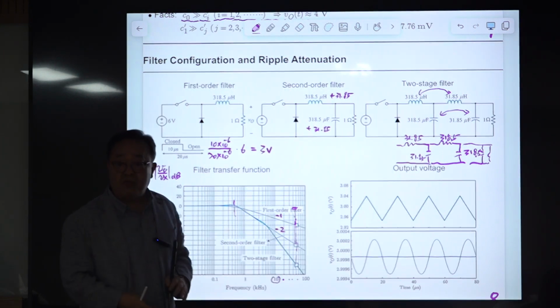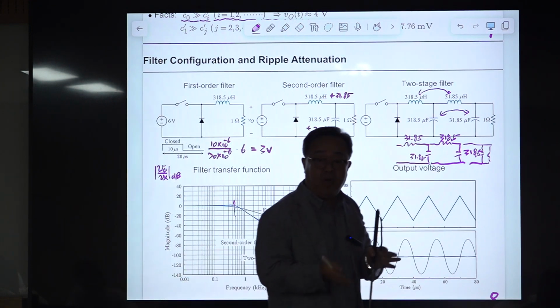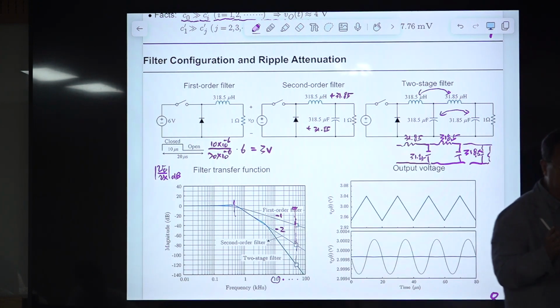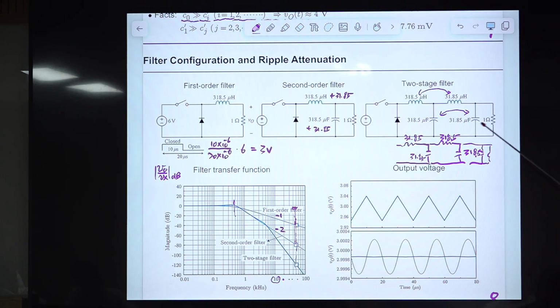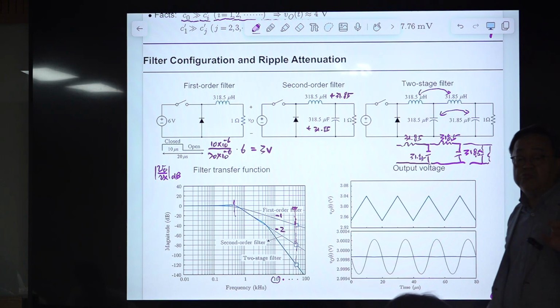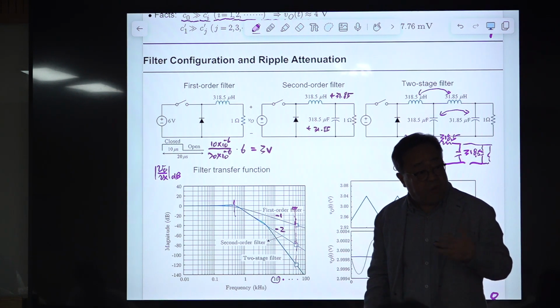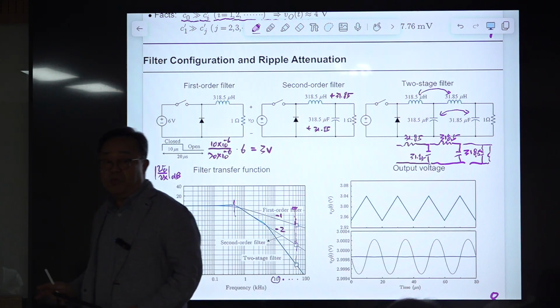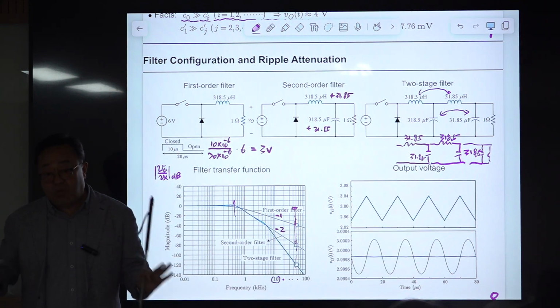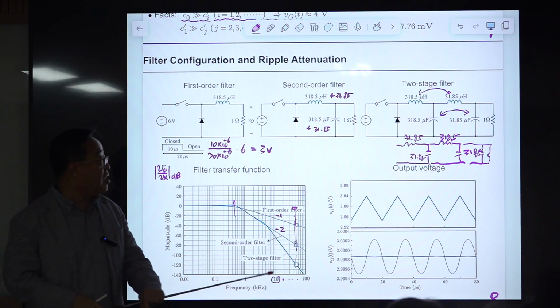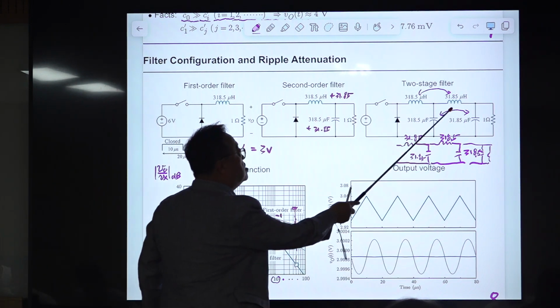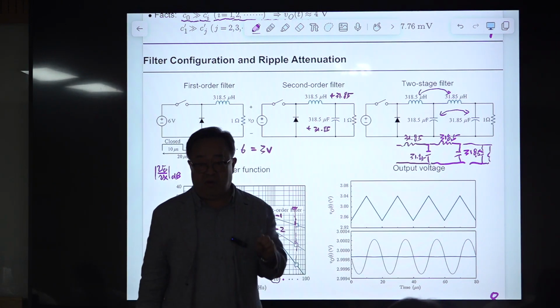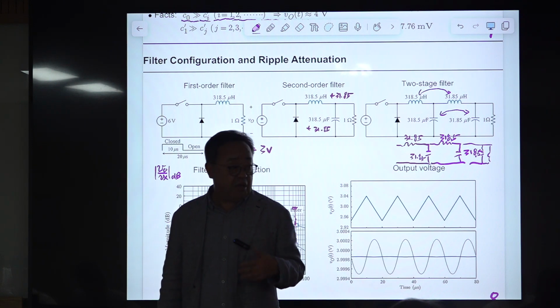When this converter, this filter, is connected to the inductive load, most of the time your load is inductive or capacitive or a combination of them or something else, very complicated. Nobody is using this resistor. This is for experimental purposes in your laboratory, and simulation purposes to study the principle of the buck converter. So in practice, there is no resistive load. Okay? So for that case, just swapping this position will provide a lot of benefit in practical application.